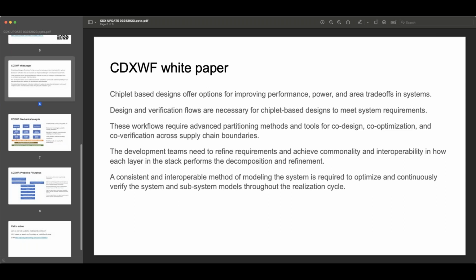As you know, and are learning, a lot of the typical flows which you would have for monolithic SoC have been serialized, in the sense that you would start with RTL, then design your die, then design your package, then do a sign-off, power integrity, signal integrity check.